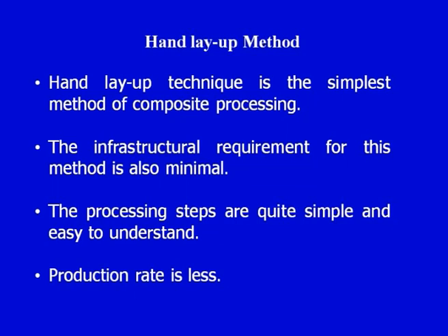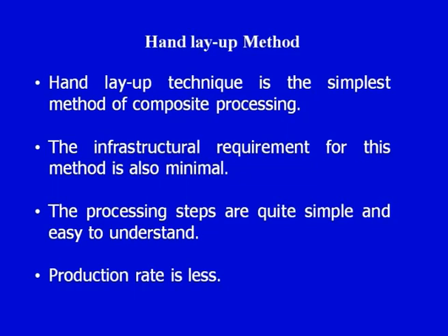Now, the first and foremost process and the most common process that is used for processing of polymer matrix composites is the hand layup process. So, hand layup method or the hand layup technique is the simplest method of composite processing. It is the most simple method and the needs and the requirements are not that stringent. Even a very simple mold can be used for processing using the hand layup technique. The infrastructural requirements for this method are also minimal.